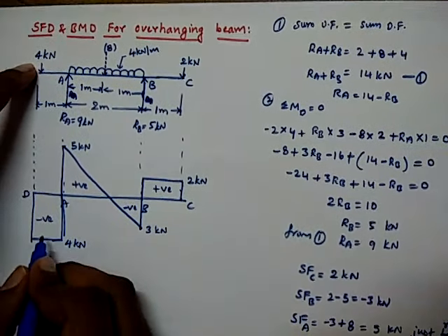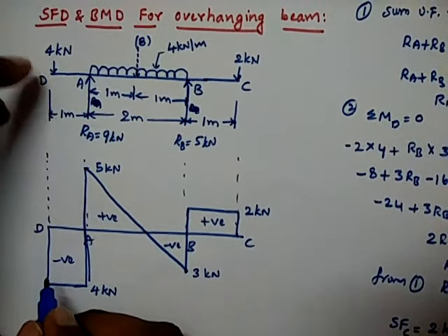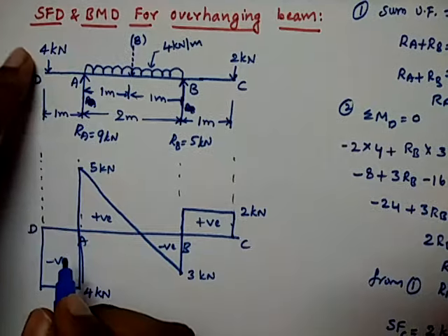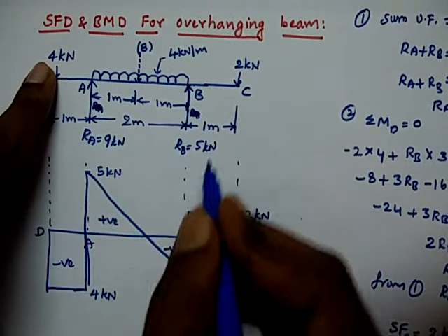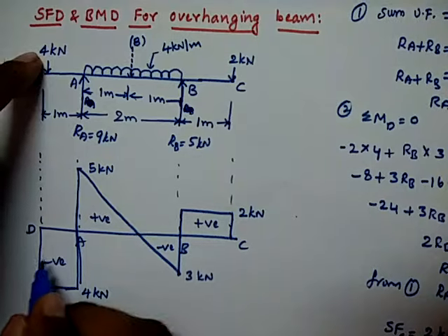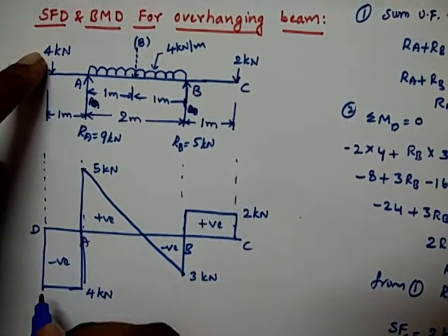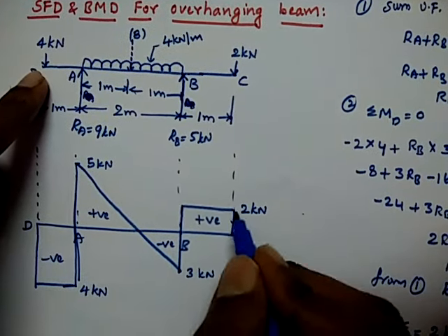And if you see the force here, it indicates the force acting at D, the point load acting at D. So in our process don't take this load, since we are coming from right to left, so the last load should be neglected. It is a shortcut method to draw this diagram, or if you start from here, you just don't take this, such that it will indicate the 2 kilonewtons here.